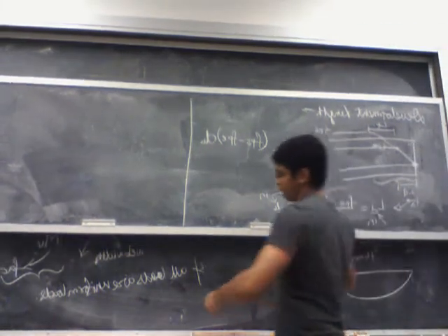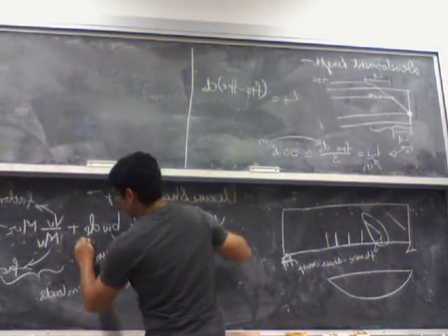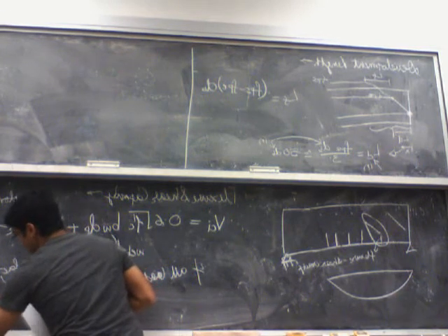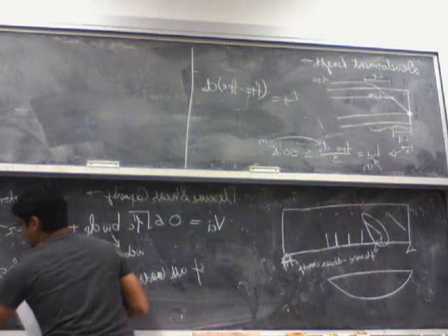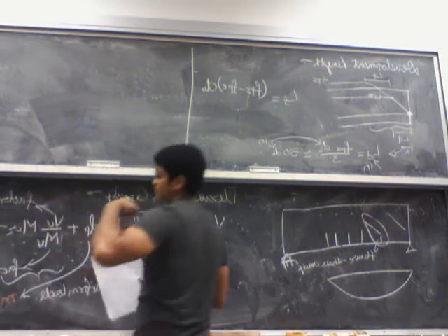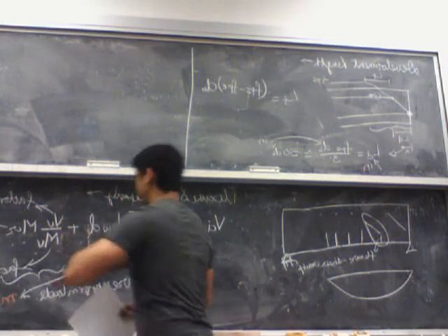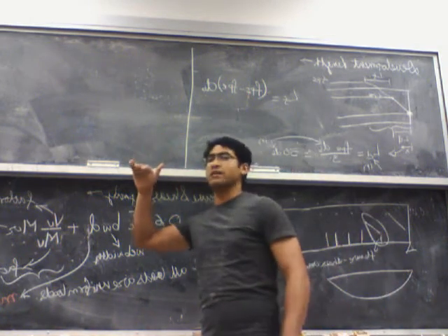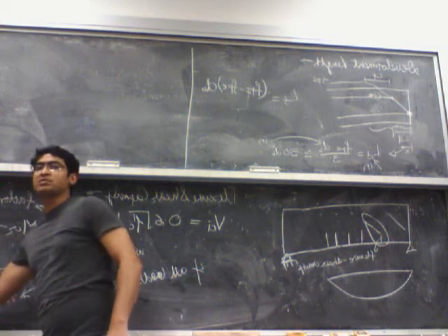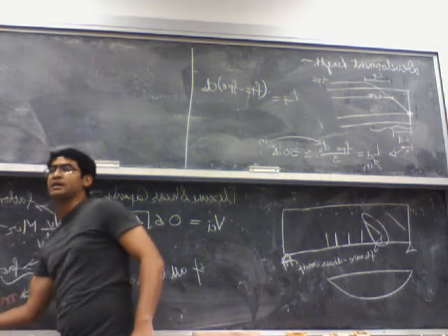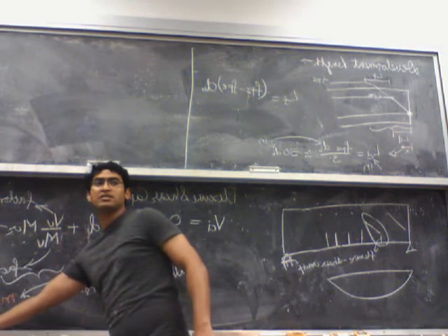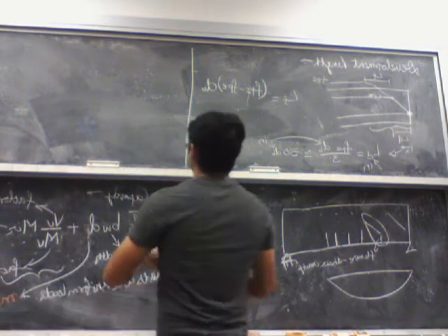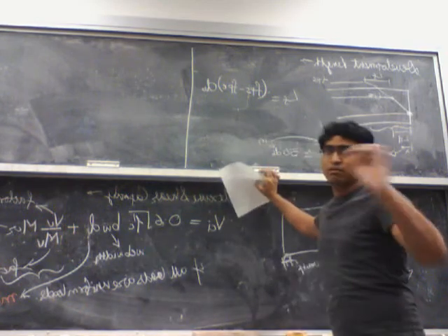One more thing, this d_p, it is the maximum of the actual d_p, that is the distance to the centroid of the prestressing strand, or 0.8 times the height of the cross section. So let's just call this d actually. If your strand is closer to the centroidal axis, your d becomes 0.8 times h, and if your d_p is greater than 0.8 times h, then this d becomes d_p. That is the distance from the top of the compression face to the centroid of the prestressing strand. So again, this formula is if all the loads are uniform loads.